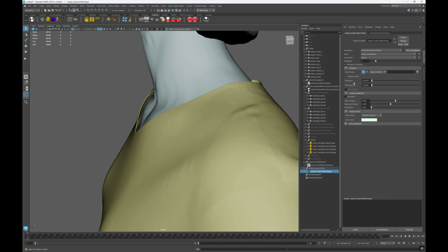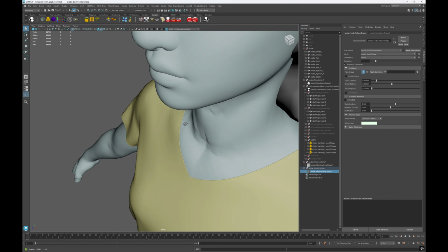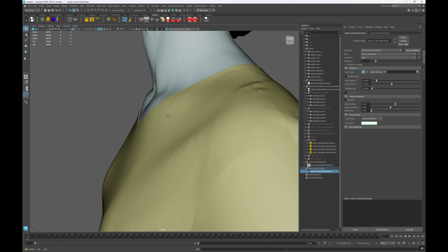So we can replicate that in carbon by going here to the collider, making it single-sided. We'll make the internal collision 1mm. The internal collision is limited to half the distance of the narrowest part of the collider. The outer collision, which we call fatness, already said we need to make it 4.25. So that is replicating essentially the conditions in CLO. The difference here in carbon is we're going to actually expand the size of the avatar by doing this. Okay, so now you can see we've expanded the avatar. There's no gap now between the garment and the avatar.